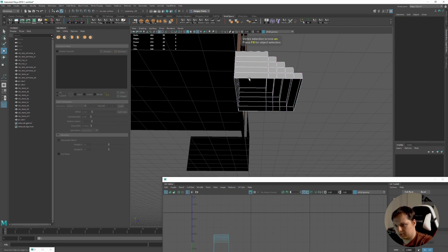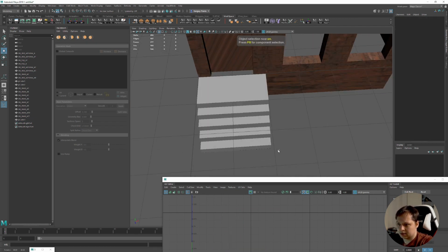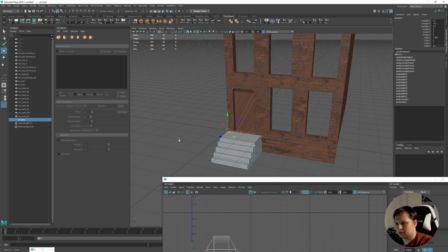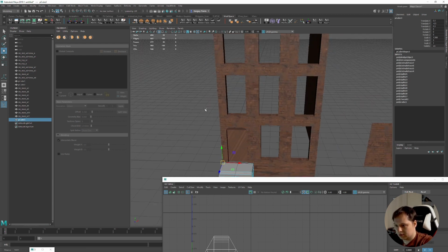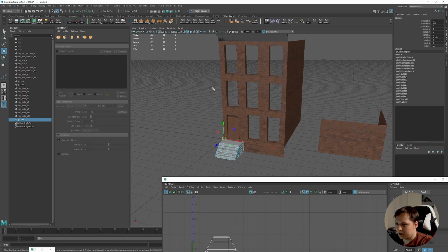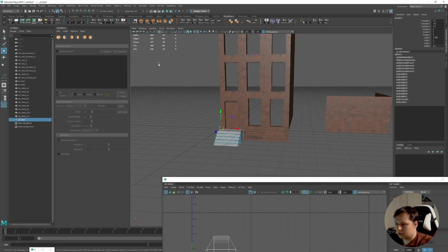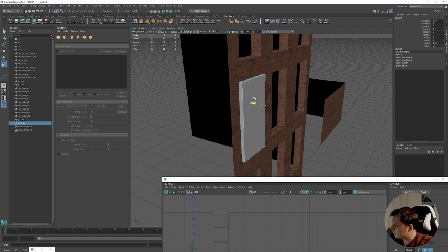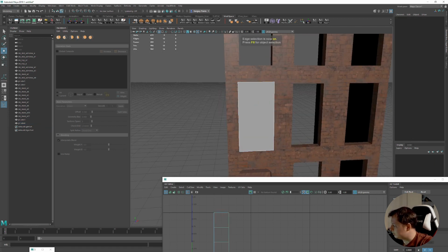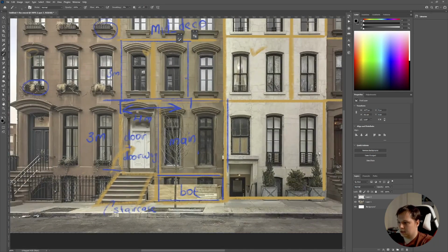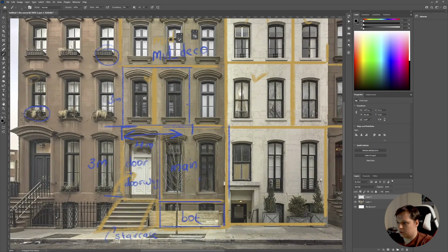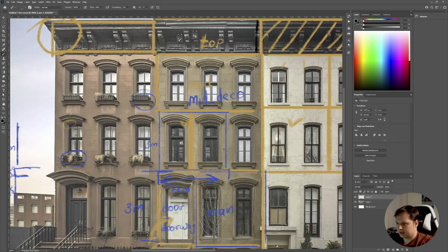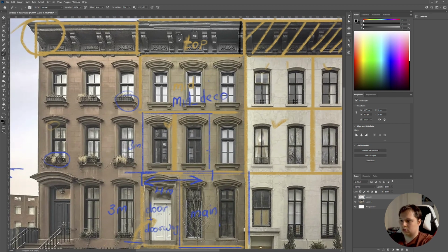And I will not make this mesh hollow. There are a couple of reasons why it's still good to have your mesh not hollow. Mostly it's LODs. The LOD system does not like hollow meshes. So yeah, I would prefer to do it. So now let's very fast do our window modules. This will be the default window, because if you remember I said that I will do a default window and then the decoration of this window will be different. So all of them will have this kind of shape in the initial mesh, but the decoration will be different.